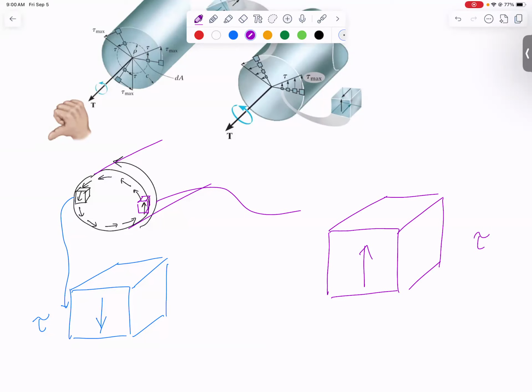Do you remember equilibrium a little bit with shear stress? If you have the stress pointing downward on the front face, there would be this hidden back face. Let me draw it with some dashed lines. The hidden back face has to have an equal and opposite force on it, right? Force comes when you take this shear stress and integrate it over the area, or sum it up. You'd end up with an overall net downward force on the front face. It's got to be countered by an upward force somewhere else, so we assume that's on the back face. Same thing with this purple one. If it's upward on the front face, you will need another one that is downward on the back face.